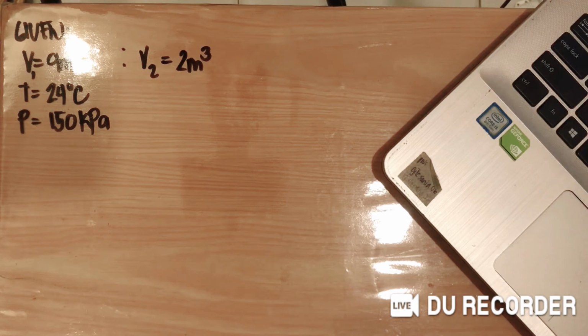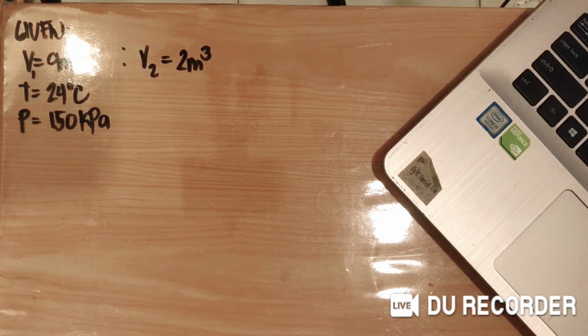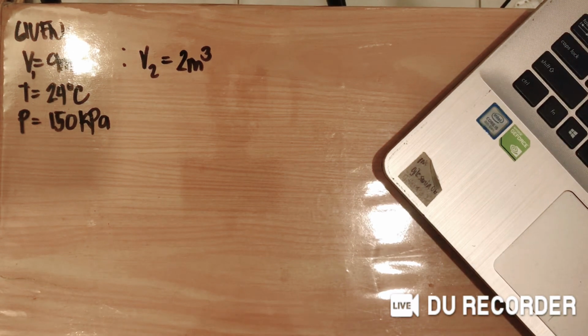Okay. Then next, determine the resulting pressure assuming isothermal conditions. So based on our notes at slide number 22, for the property changes in ideal gas, for any ideal gas experiencing any process, the equation of state is given by the ratio P1V1 over T1 is equivalent to P2V2 divided by T2. When temperature is held constant, equation 1-18 reduces to Boyle's law. So the formula for Boyle's law is P1V1 equivalent to P2V2.